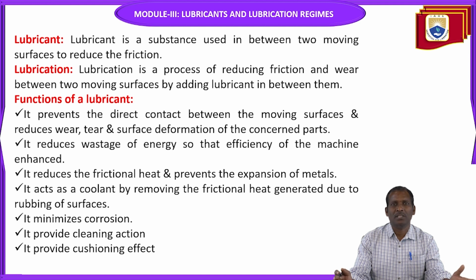By doing this, you can avoid failures. It minimizes corrosion. It provides a cleaning action. It provides a cushioning effect. To smooth out high vibrations, you can use this lubricant. It acts as a damper.